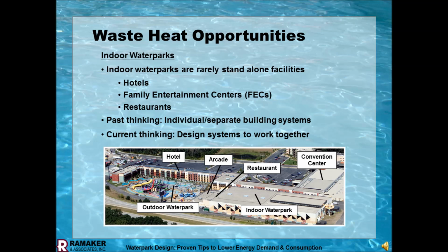Well, that's just dumping heat out the window if you're using PTAC units. If you go into a 2 or 4 pipe system and get a water heat source loop running around, you can take that heat that's being dumped out of the hotel and put it into the water park.